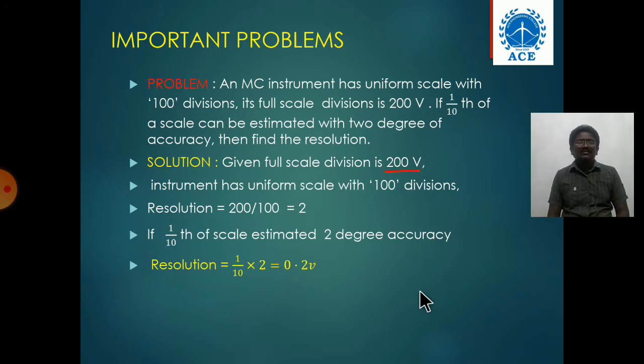So next one, DC ammeter. With the help of an ammeter you can measure current. Generally here we again have three extension types of the DC ammeter. First one, multi-range DC ammeter. With the help of this circuit you can calculate a number of shunt resistances and a number of current levels.